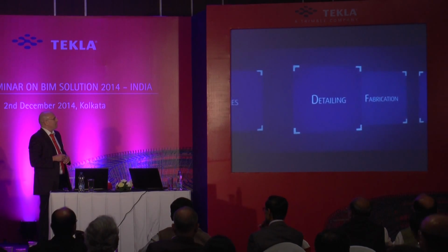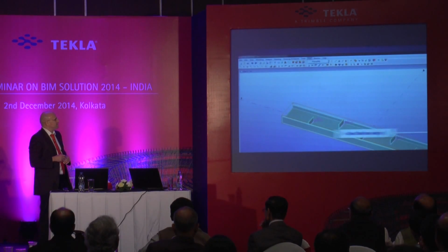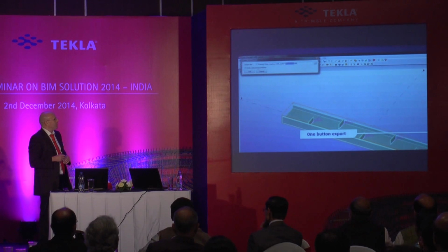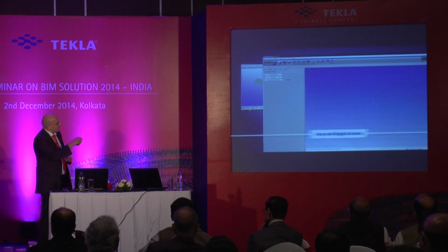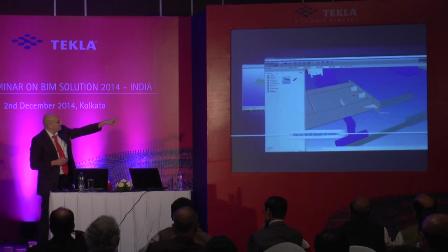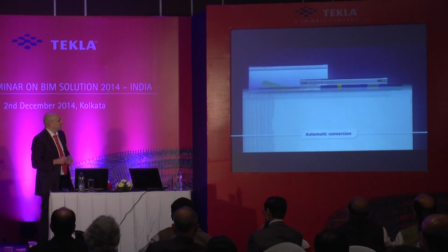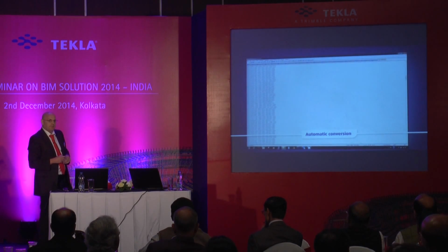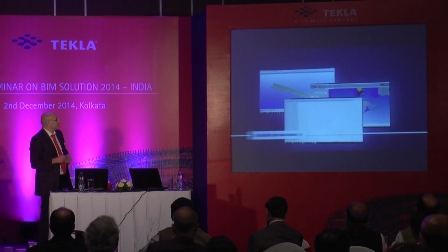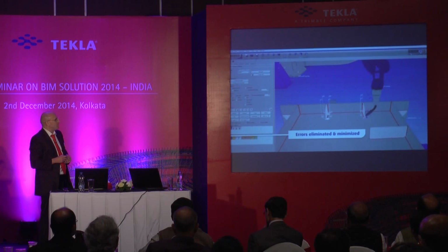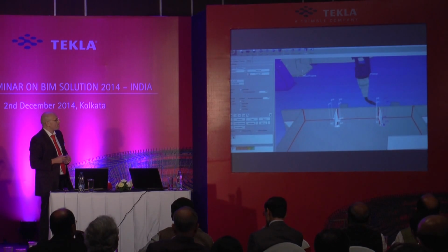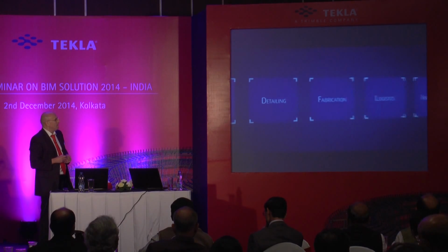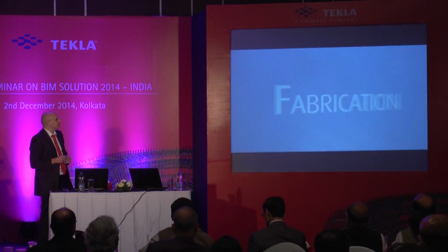So then you've got your detailing model. So there it is, that's your Tekla model there. You export the data out. If you've got a welding robot, you can export it out, import it to their software, and then you get the same piece in their software, and that's the representation of the welds. And then you send that down to the machine in the workshop. Then for the machine in the workshop, you've got the little simulation that shows how it's going to operate when it gets there. And then down to the actual workshop itself.